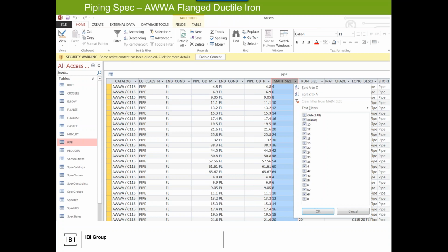In the Revit world, there are piping tables. Revit used to be much weaker on the piping side, but now there's a lot more control. But in Revit, it's very non-industry standard in that you can put whatever you want into it. You can make pipes that are 2.6565, whatever. So here you're restricted by the industry standard, and then you can further restrict what can be done.